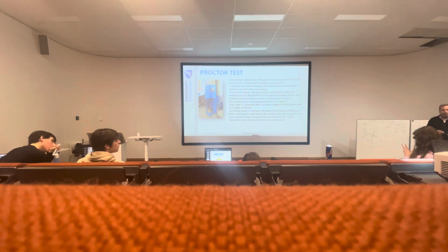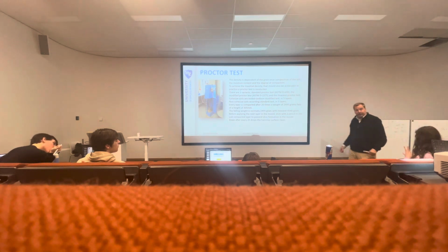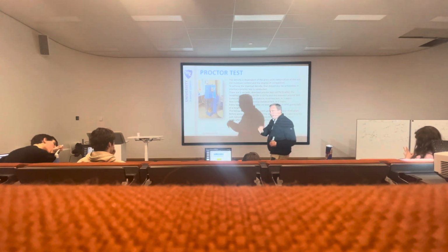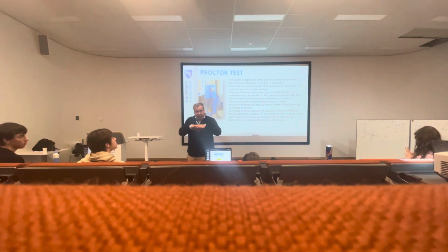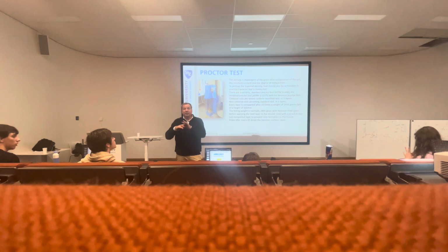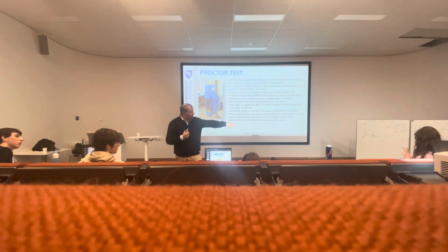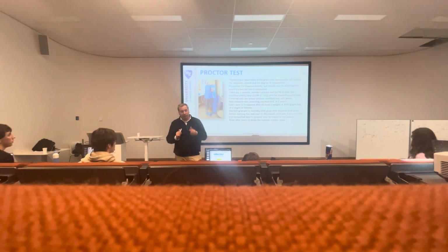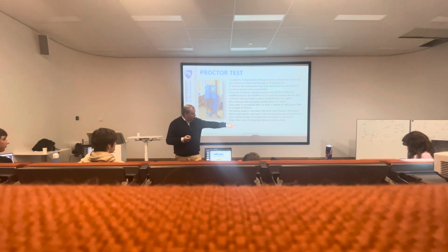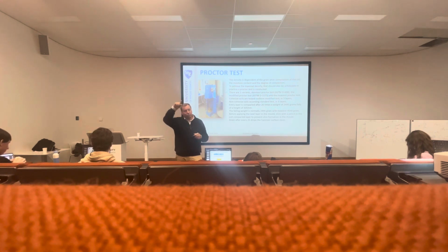So basically what you have, you take a soil, you add some water to it, you start compacting it until the cylinder is full, you measure the density, so you have a certain density, then you take a part of that soil, you measure the mass, you put it in the oven, and after that you measure again the mass, and then you know how much moisture was inside that specific density, and that you put on the x-axis. You add some water, again and again, until you get a nice curve.